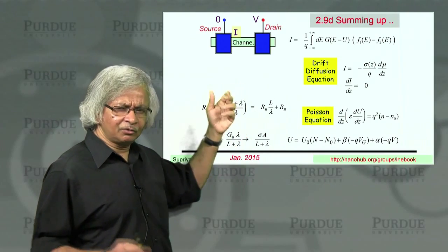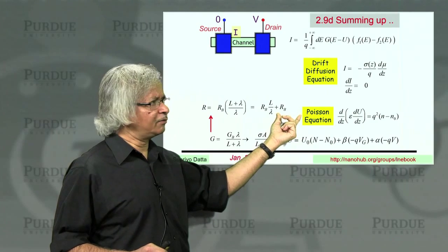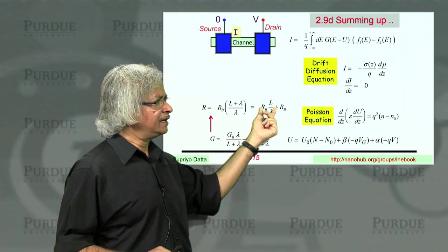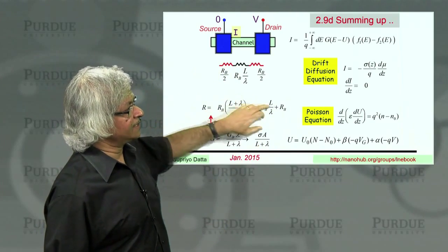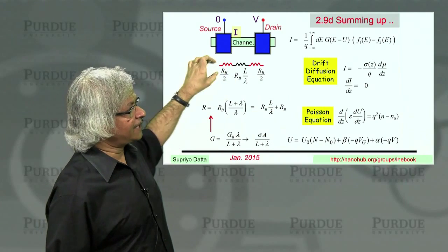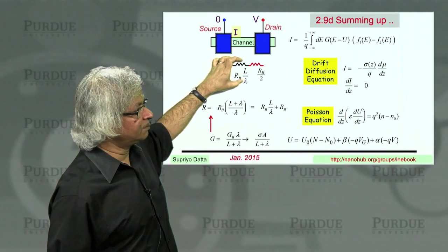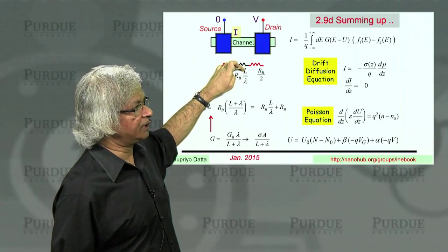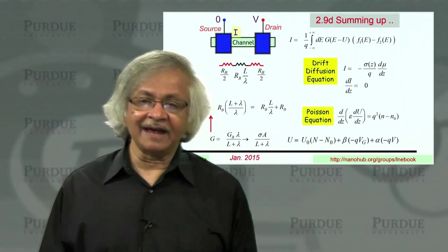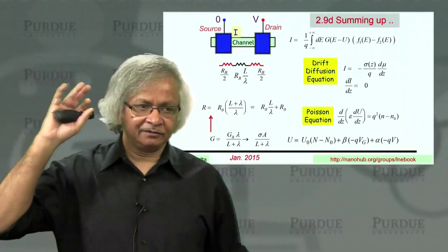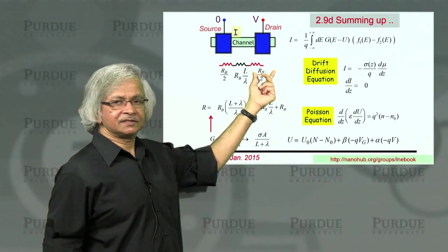But one thing we didn't quite address is what exactly is this resistance? What is it associated with, since it's independent of length? The modern understanding is that this resistance is actually an interface resistance that appears at the two ends, whereas the middle part has a resistance that's proportional to L. So the most important thing this new perspective adds to our old understanding is this idea of an interface resistance.